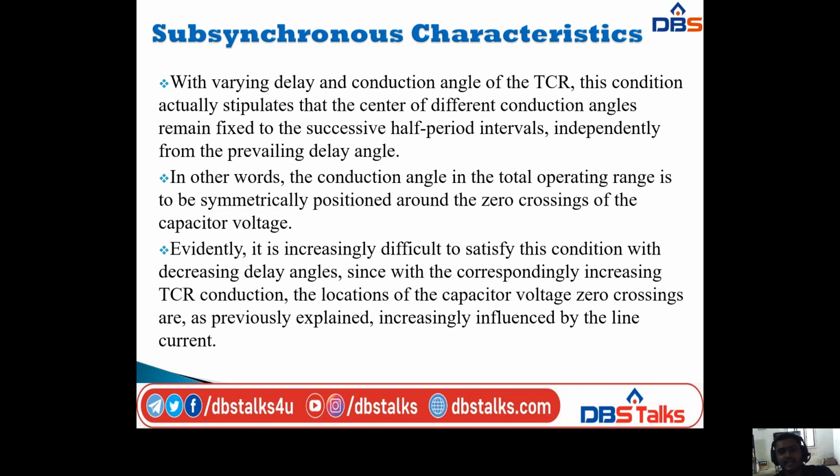So with varying delay and conduction angle of the TCR, that is alpha and sigma, this condition actually stipulates that the center of different conduction angles remain fixed to the successive half period intervals, independently from the freewheeling delay angle. So in other words, the conduction angle in the total operating range is to be symmetrically positioned around the zero crossing of the capacitor voltage.